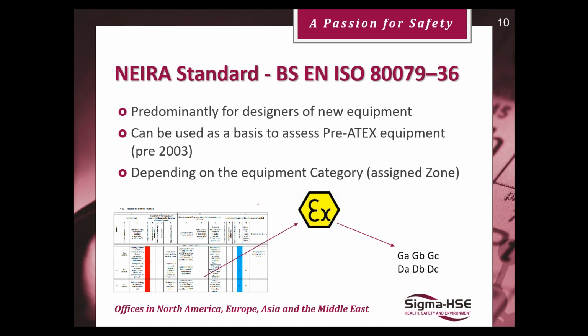There can also be special circumstances. For example, I've experienced in the pharmaceutical industry that it takes many years to get a qualified piece of equipment through validation, and sometimes the client finds out that it is using flammable materials. So although it's not legally compliant, you can still undertake this risk assessment and designate it as safe, although not certified safe, just designated safe. Just thought I'd mention that.